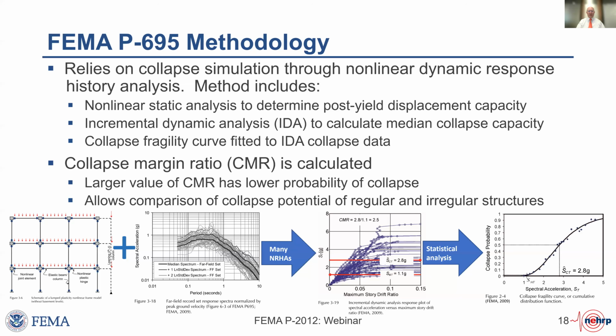That's used to determine post-yield displacement capacities. And then you perform incremental dynamic analysis. In a sense, you are shaking this model with larger and larger earthquakes to understand when it collapses, what causes collapse, and to determine what its margin against collapse is when it's been designed properly.